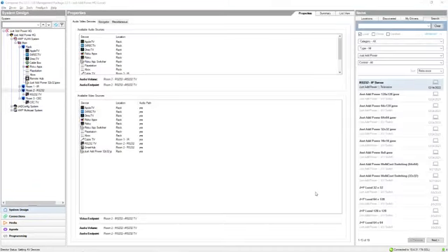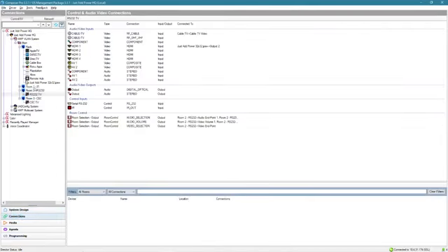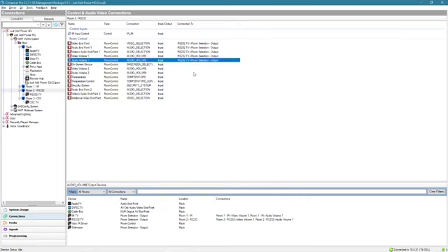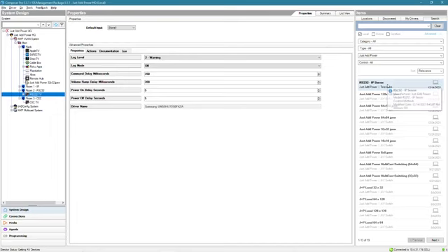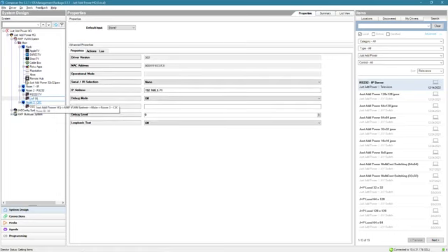Now let's look at how to control a television with RS-232. Same as IR, we're going to add the driver for the television that's actually in the room first. That ensures that it gets added as the endpoint for that room so that those commands get used when they hit the button for the room. So once that driver's been added, we're going to add a Just Add Power RS-232 IP server to that room as well. We'll name it Just Add Power RS-232 driver.